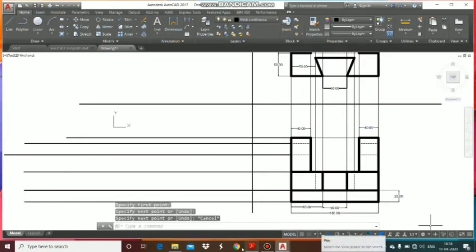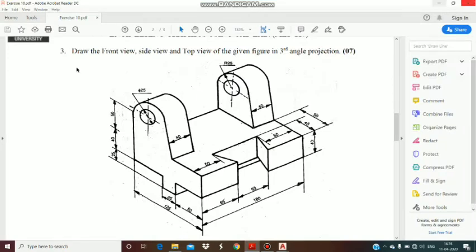Now let's see what is left hand side view. Left hand side view from this direction. If you are standing here with my cursor and looking at this figure, of this figure you can see this length, and this length. From this length up to this point, go downward, then horizontal line, a vertical line, again horizontal line, a vertical line. There is a curve again downward which is meeting here at this point, and a circle here.